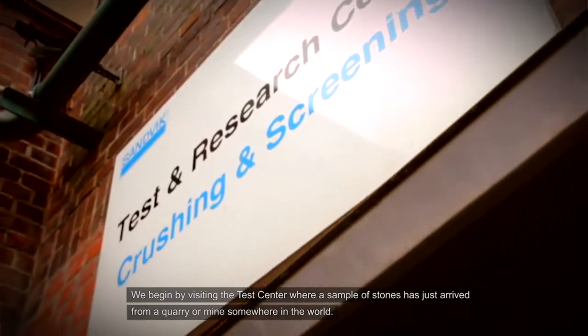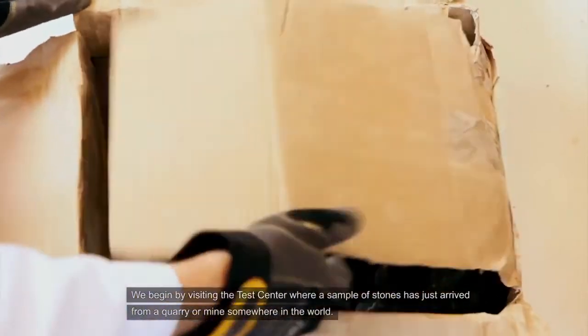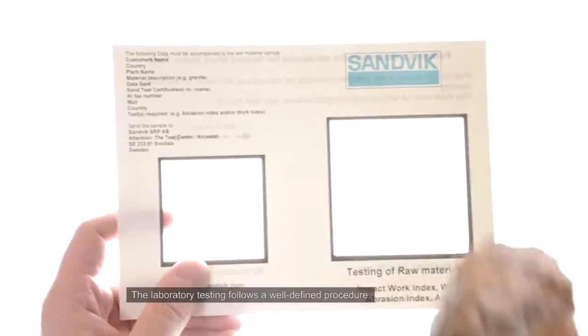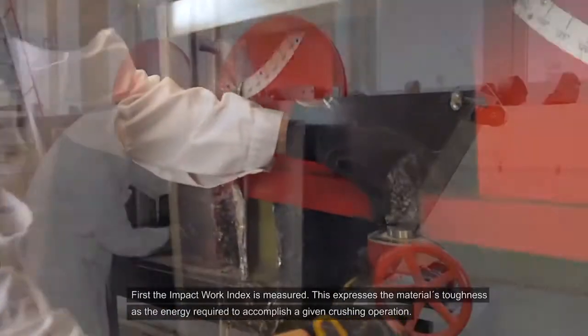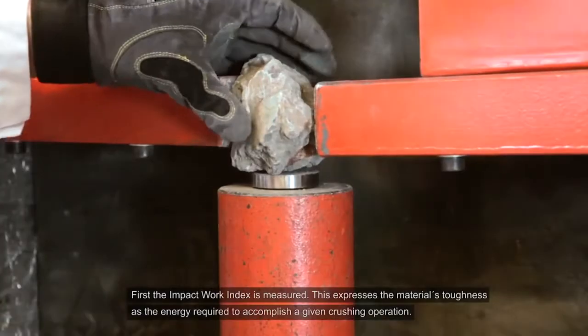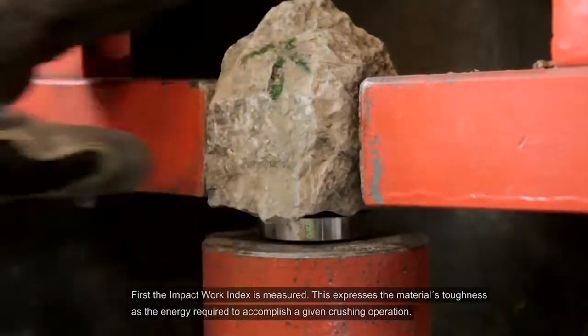We begin by visiting the test center, where a sample of stones has just arrived from a quarry or mine somewhere in the world. The laboratory testing follows a well-defined procedure. First, the impact work index is measured. This expresses the material's toughness as the energy required to accomplish a given crushing operation.